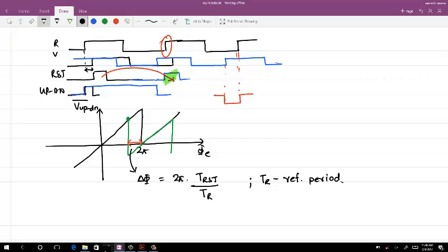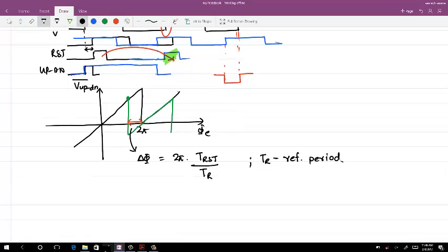So the first point is, because of this finite positive and a negative response for a positive phase error, you will actually limit the frequency range for acquisition. Okay. Now, the question I am asking is, what is the maximum T reset which you can tolerate before your frequency acquisition range actually gets severely limited, where the average goes to 0? Pardon?